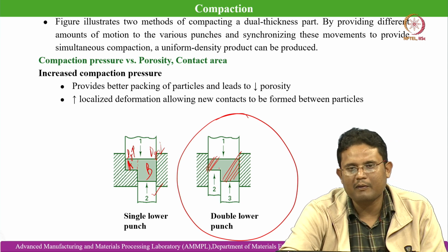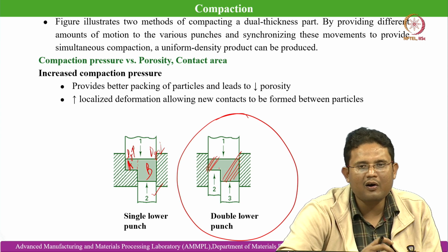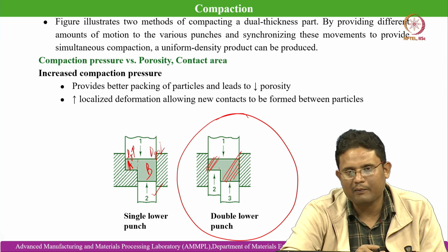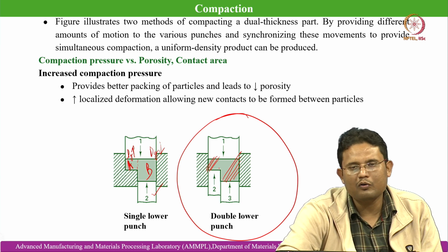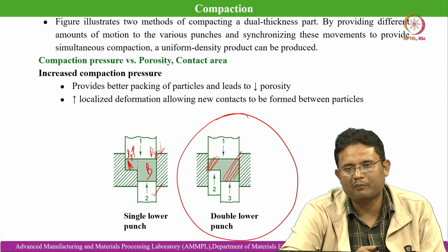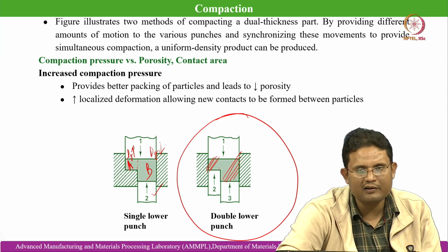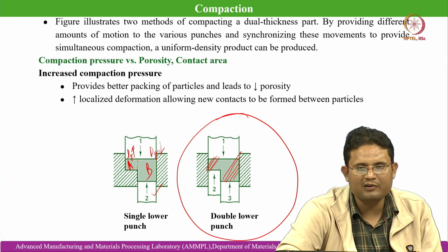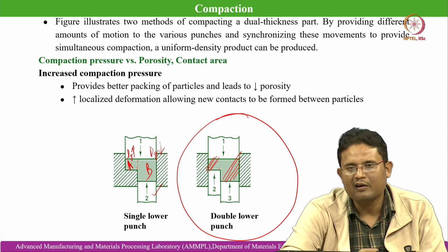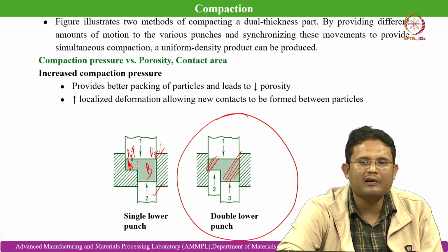Why are the powder particles not just dismantling from each other? Because during compaction we basically allow the powder particles to form cold welding at the contact points, and this is the process which is responsible for allowing the powder aggregate to retain its shape post compaction. Those cold welded regions serve as the locations from where the sintering densification starts.